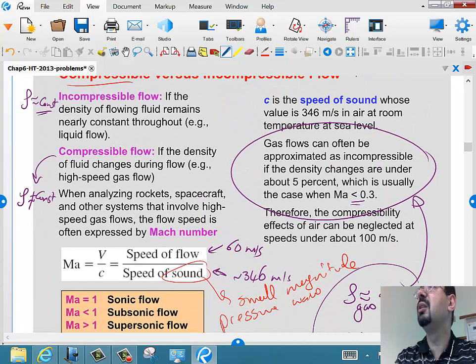346 meters per second. So in most applications, we move lower than this. We move less than 100. The wind tunnel we have in Min Hole, the maximum velocity there is like 60 meters per second. So it's definitely less than 100 meters per second, which is Mach 0.3. So we think that air moving in the wind tunnel basically has the same density, 1.2. Okay?